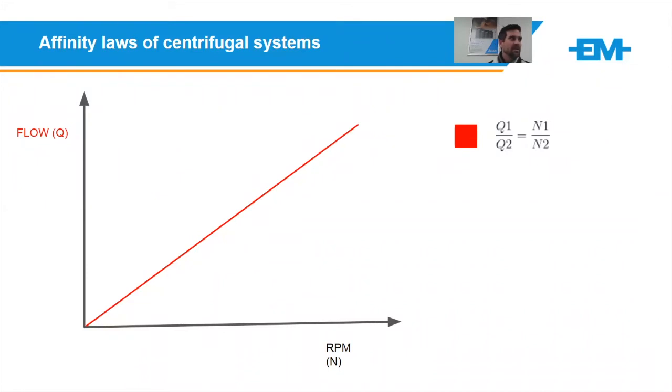You can even compare the default parameters versus the parameters in the drive, and tell it to highlight only the settings that have been changed from the default. It normally is just a handful of parameters that you need to look at, not a long list.